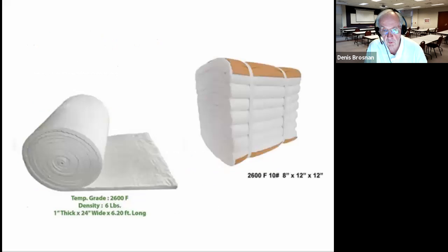So here's the difference between a ceramic fiber blanket. You can see the blanket being unrolled there in this example. When these products first came out, they were laid like wallpaper on a wall and anchored to the wall, but it was found that this type of construction was susceptible to tearing of the fiber, especially when there's draft imposed upon the fiber.